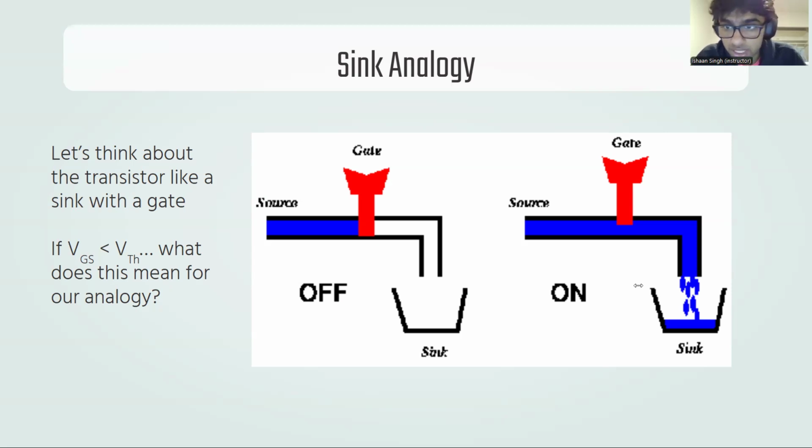You apply a negative voltage to the gate. So yeah, if you apply a negative voltage to the gate, it's like you're below the threshold. There's depletion and enhancement mode NMOS transistors. We won't talk about those. But for our purposes, the threshold voltage is always positive. So if the gate voltage is negative, you're not going to meet threshold voltage, and that's that. You're done. Game over.